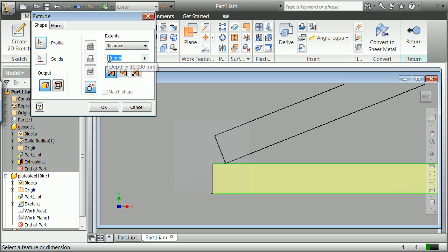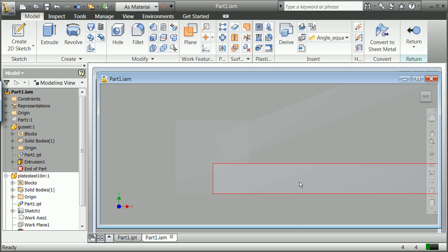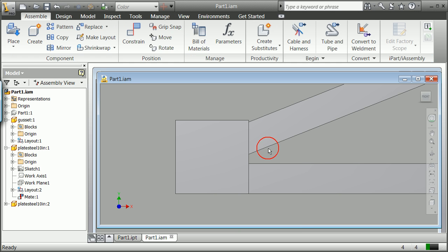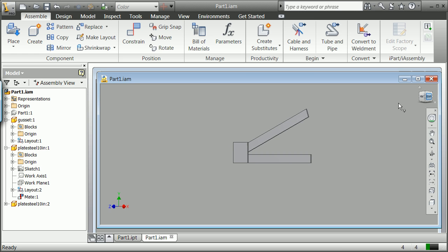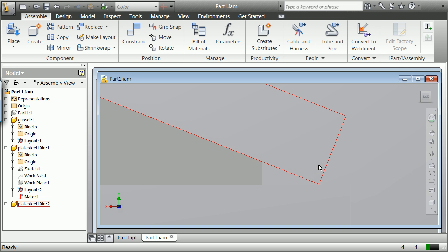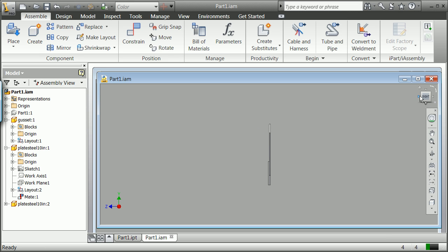This time we're going to go 25 millimeters in. I don't know why that went to millimeters. I think it might happen naturally. Click that. We're going to push that one down. We are going to right click over the gray space, finish edit, and you see that this came out 25. This went down 25. We'll do it one more time. I think we don't even need to because those are the same block. What we've done is we've converted these blocks to parts. So they are no longer sketch blocks, but they are parts, and you're pretty much there with what you need to do now in terms of putting in holes.